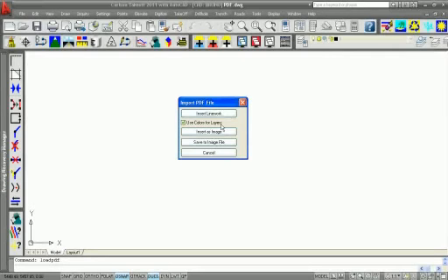So when you get that PDF from an engineer or whoever you're getting it from, the program will be able to recognize if there's any grayscale. It's going to be able to recognize those colors in the PDF and put those out onto their own layers, a process that you don't have to do. With the last release, when you brought in a PDF, everything came in on the same layer 0. So now, whether it's in color, if it's red and blue, or if it's in a different grayscale, that PDF, we're now going to get layers from it.